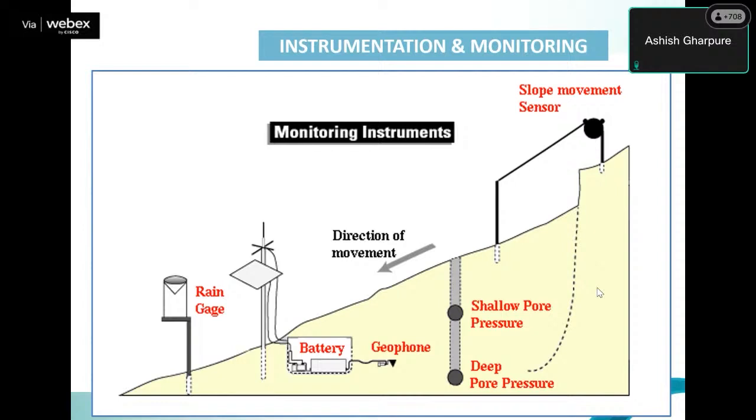If you try to do risk elimination, a 100% guaranteed slope, I get these things thrown at us also, that whatever you do, it must be guaranteed. In a hill area, if you are giving a solution, a guaranteed solution may cost you, say, 1,000 crore, whereas a 90% solution can cost you maybe 100 crores only, right? So guaranteed solution is a term which should not be used. We should use a financially viable solution, technically and financially both viable, then it makes sense.